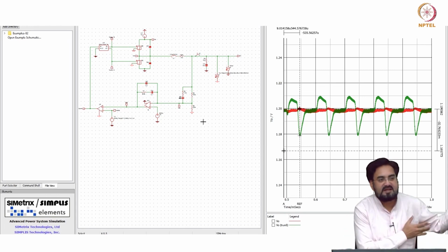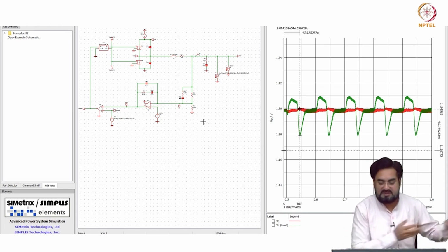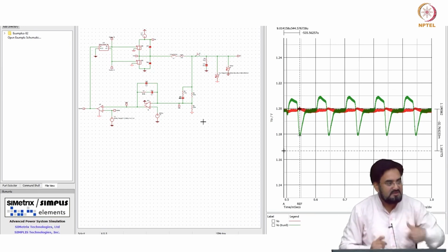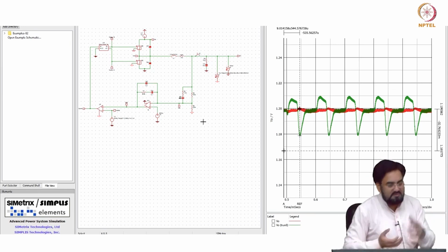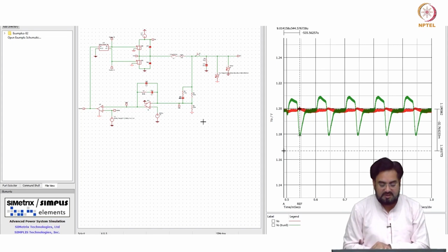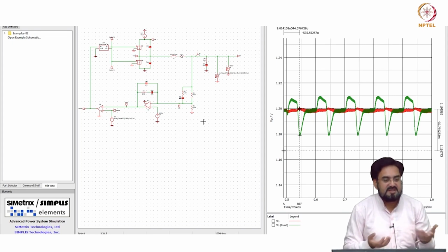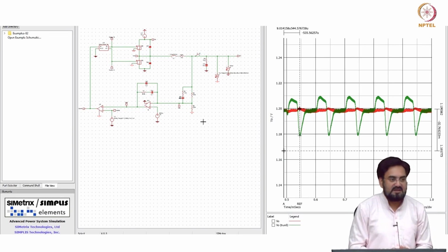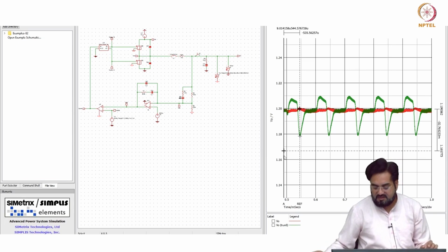If you look at that gain, we are getting 100 times, which means this should have been on the order of maybe volts, but it is not large because it gets suppressed up to some point by the loop gain. That suppression depends on how much loop gain you have in the feedback, but it may still appear if you do not have those poles added in your compensator. Okay. And you can see here, we can measure this peak to peak.